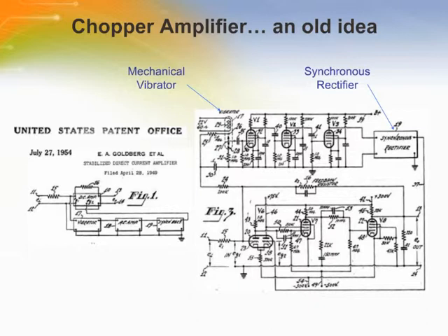One of TI's main innovative focuses over the last several years has been in zero drift technology using chopper amplifier circuitry to minimize voltage offset and drift. Chopper amplifiers themselves are not necessarily a new idea. The first chopper amplifier patent was filed in 1949.